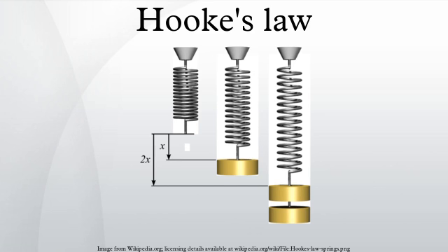General scalar springs. Hooke's spring law usually applies to any elastic object, of arbitrary complexity, as long as both the deformation and the stress can be expressed by a single number that can be both positive and negative. For example, when a block of rubber attached to two parallel plates is deformed by shearing, rather than stretching or compression, the shearing force and the sideways displacement of the plates obey Hooke's law. Hooke's law also applies when a straight steel bar or concrete beam, supported at both ends, is bent by a weight placed at some intermediate point.